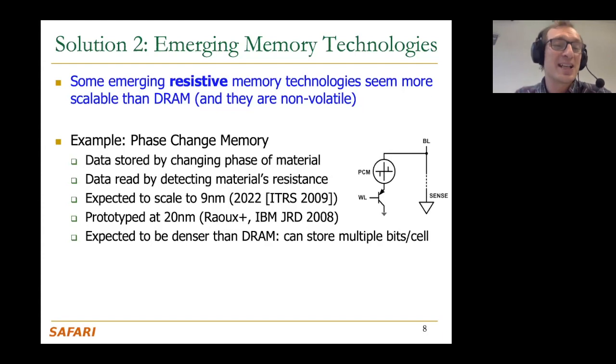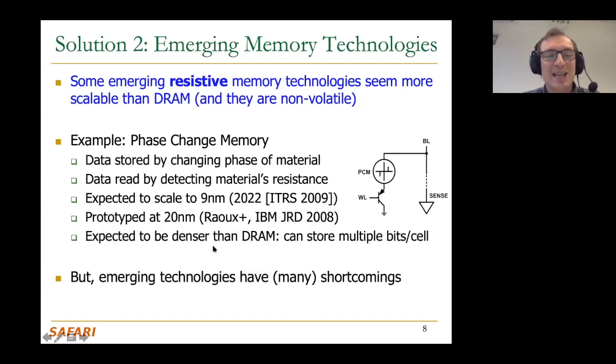So this technology already exists, except clearly you can imagine that this sort of reading process is a very slow reading process. More recently, people have focused on enabling a read device for phase change memory that's much more compatible with existing memory technologies, sense amplifiers, basically. And they were very successful. As a result, we have phase change memory in the field today. Okay, so I spent more time, but it's good to understand that these things exist.